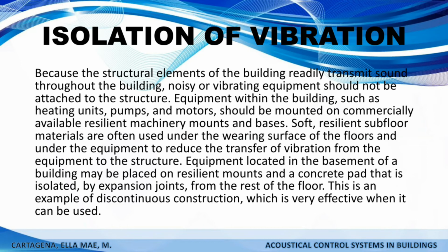So, what is vibration? Vibration is unwanted motion that is transmitted to the building structure and occupants, generally from rotating HVAC equipment. So, sound is produced when an object vibrates. So, the equipment inside the building, like the heating units, pumps and motors, should not be hung from the structure. They should be mounted on commercially available resilient machinery mounts.